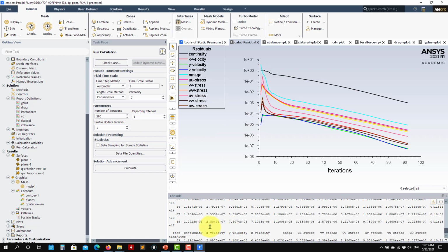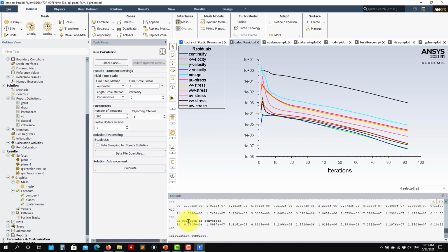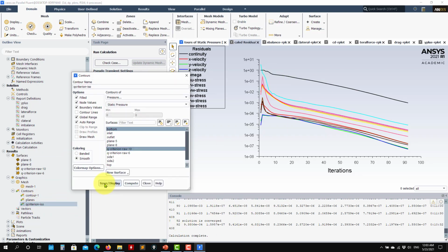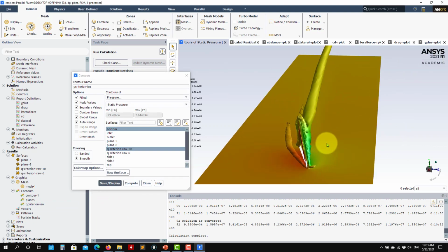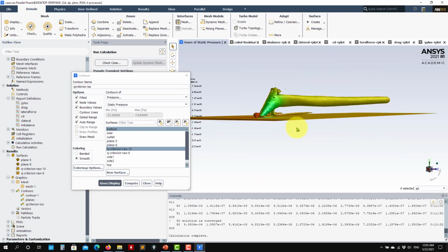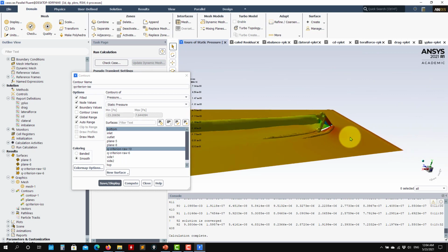See that everything is smooth, no funny messages about having negative normal Reynolds stresses. Remember that those by definition should be positive because it's the fluctuation squared, so there is no way that it becomes negative, but numerically speaking it might happen, and it was happening in the previous cases. In this case everything was smooth, and again we can go here and plot and capture this. Okay, so see that you have the horseshoe vortex here, another vortex here. You have all your vortical structures.